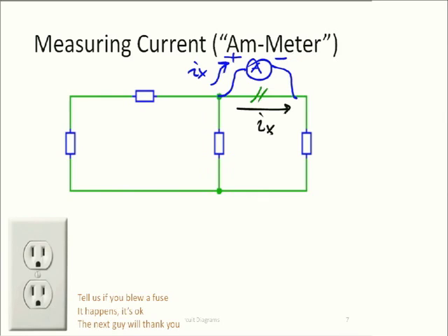They make sure that the current runs through the right prongs and not somehow through you, by comparing the current that's flowing through these prongs and this funny earth prong. We could talk about this once. If you're interested, come to my office hours and look at it. But anyways, these GFI terminals, those are these breakers that have a little button at the top to test and another one to reset it. Do you know where they were invented?